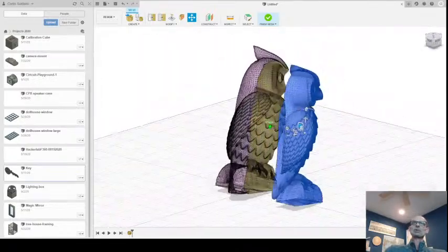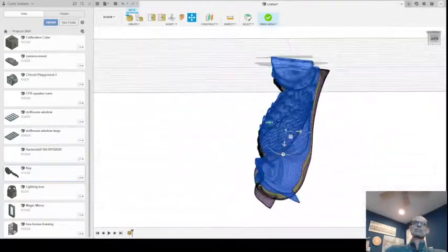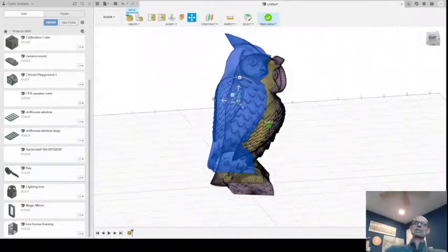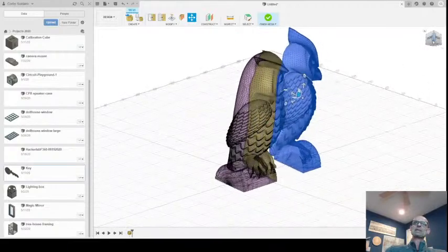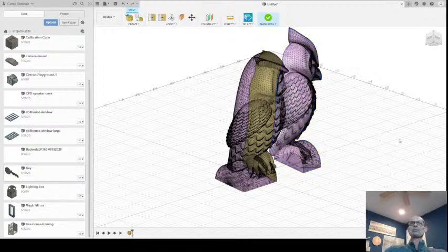So we cut it, right? There's a hollow on the inside that we can then apply some repair tools to. Those are the two pieces, we split them up. Let's say I want to make a closed mesh, so it'll take this open mesh and close it. Let me make closed mesh, select that one.